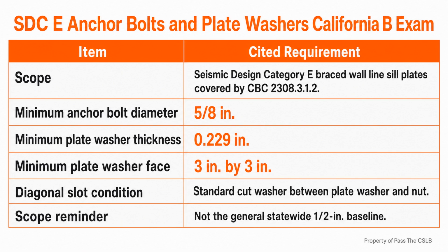A non-structural convenience change and a seismic load path change are not the same category of decision. When a proposed change touches the route that transfers shear or uplift to the foundation, I treat it as a design-controlled item. I use a top-to-bottom inspection habit because it mirrors the direction of the handoffs. I start at the roof or floor diaphragm shown on the plans. I verify that the sheathing, blocking, boundary framing, and specified connections create the intended transfer into the vertical wall system.